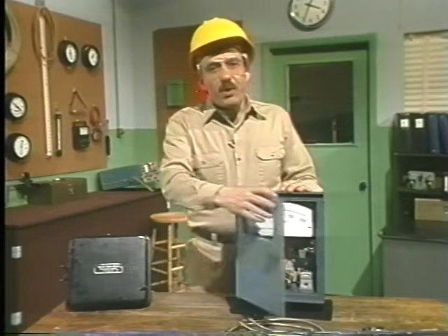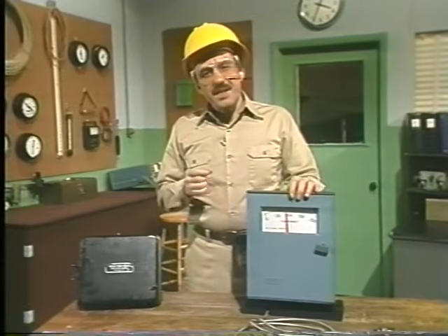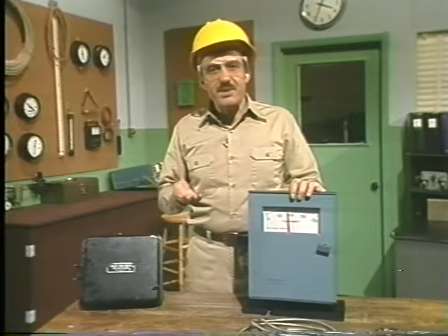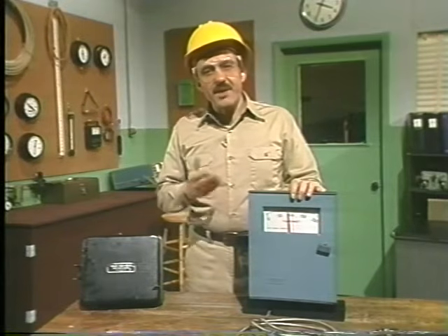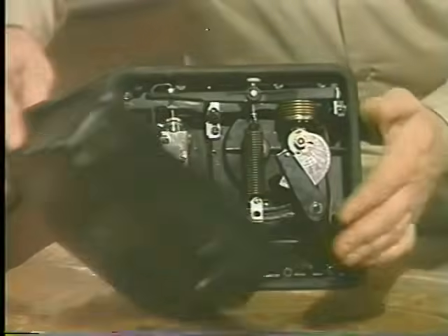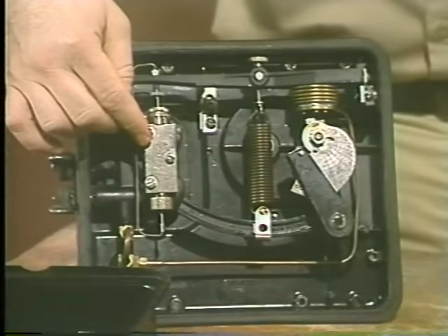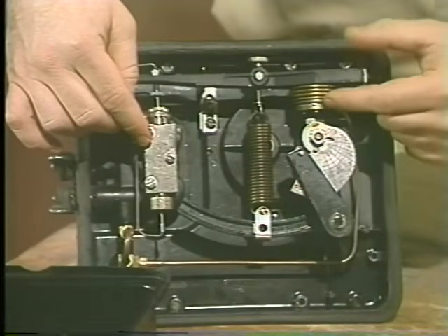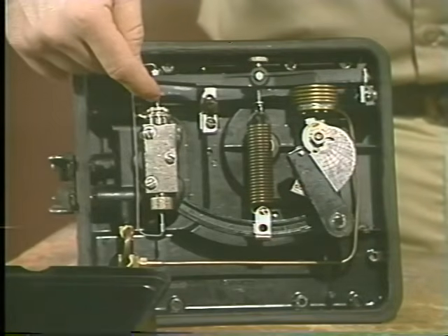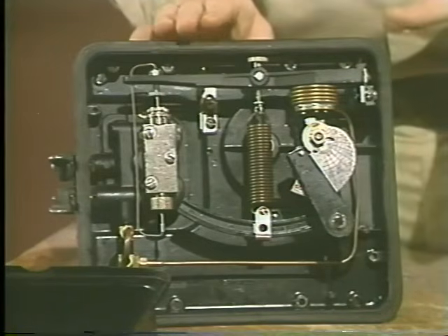Okay, now before we got into this whole discussion of flapper nozzle error detector mechanisms, I said that there are two basic types of error detectors. The type we looked at first was flapper nozzle devices. The other type we can see is in this positioner. Now, this error detector is an example of a pilot motion detector. Generally, when the input bellows expands, it lifts this beam, which positions a stem within the detector. We'll see how this works in greater detail later.